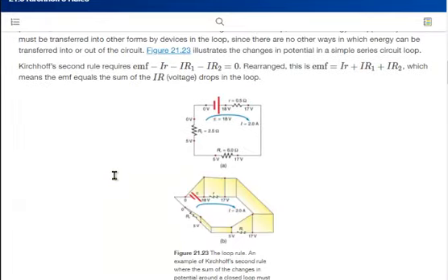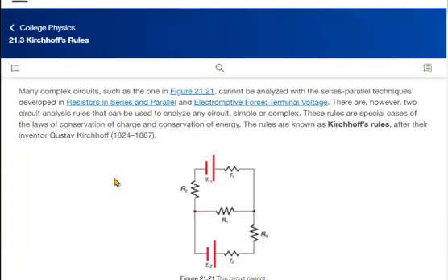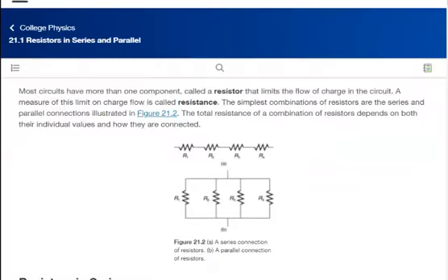Okay. The other one, here's the second rule, is just as easy. It actually looks a little bit too complicated for me here. So here, for example, we have a battery of 18 volts, and now these 18 volts of the battery are distributed in this series circuit. This one here takes 1 volt, then this one over here takes 12 volts. Just calculate 17 minus 5, which is 12. So 1 volt here, 12 volts here, and 5 here. You add the 3, you come up with the original 18 volts. And that is what's called the loop rule: when you go around, you arrive at the same voltage with which you started out. Again, makes total sense. So one of them is the loop rule for the voltages, and the other one is the junction rule for the electric currents.